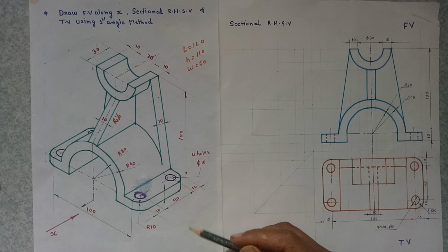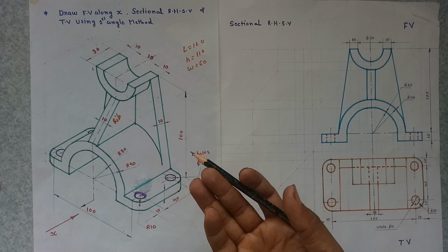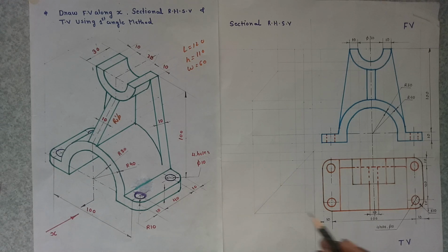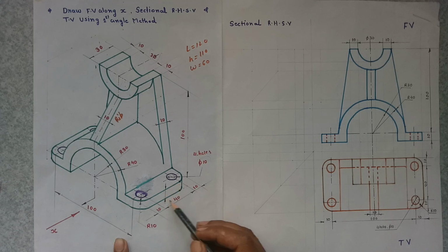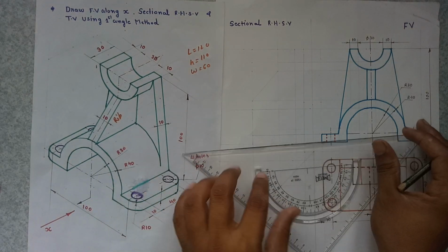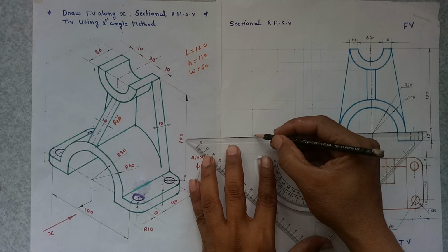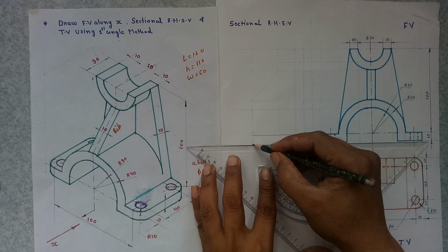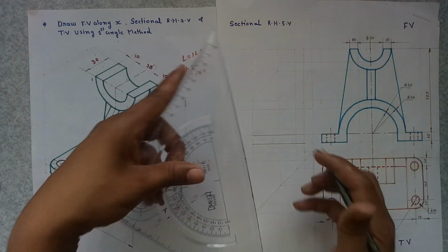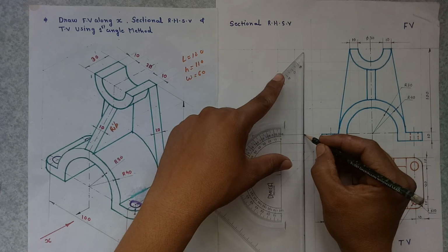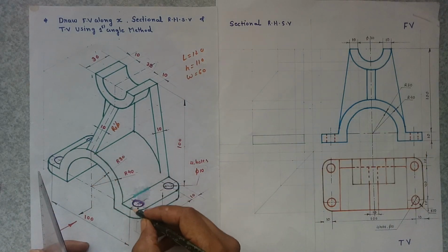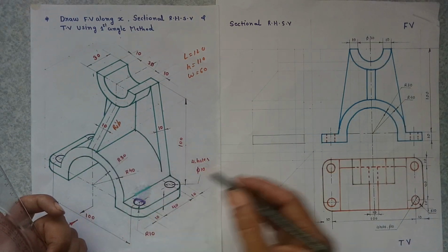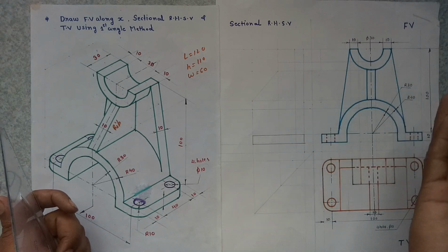First of all we will draw the right hand side view, then we will convert it into the sectional right hand side view after taking the section. So first of all, the right hand side view. In the right hand side view we will observe this particular plate as a rectangle. Projecting it from the front view, this part will be a rectangle. Then this edge is also a rectangle, up to the outline of these circles. So project these circles from the front view.